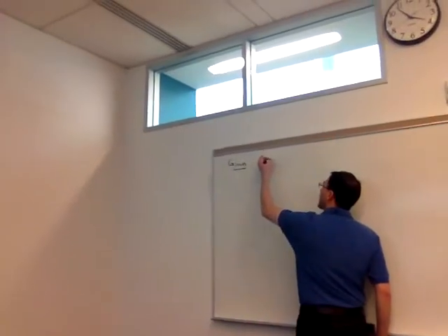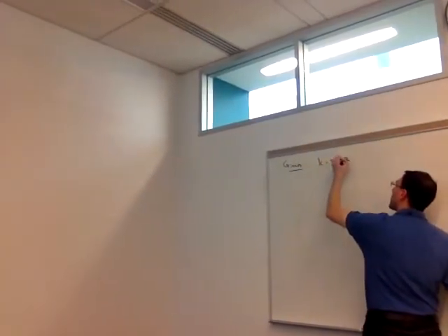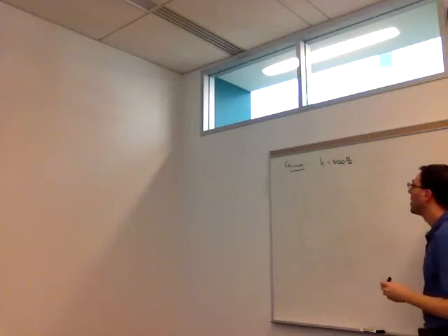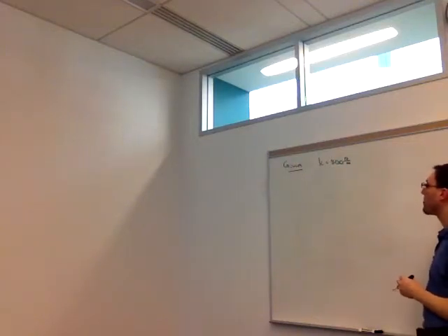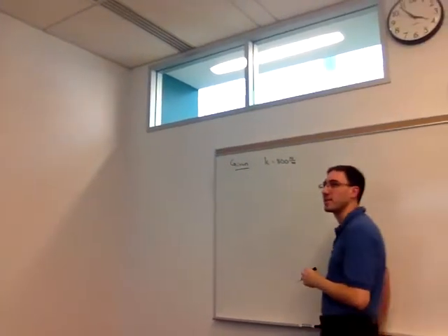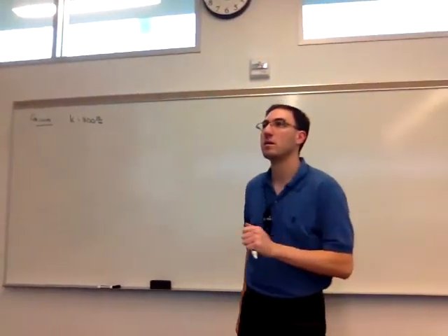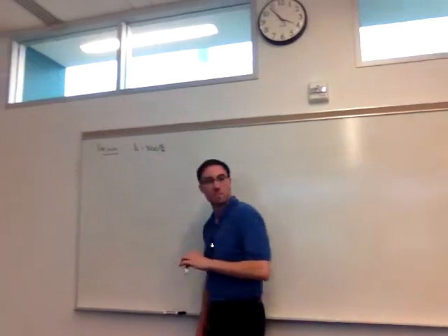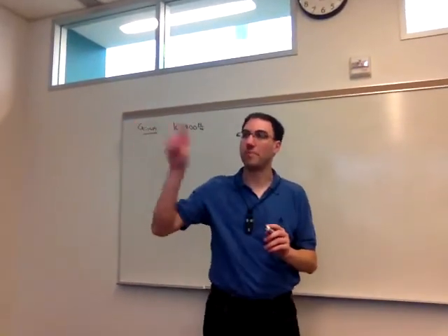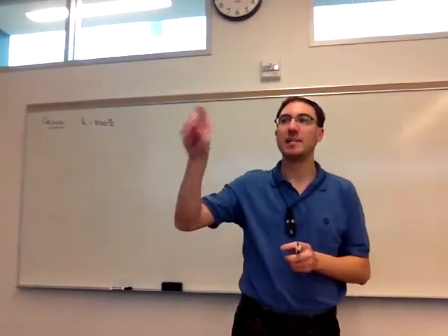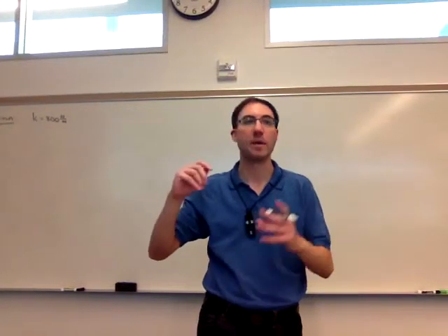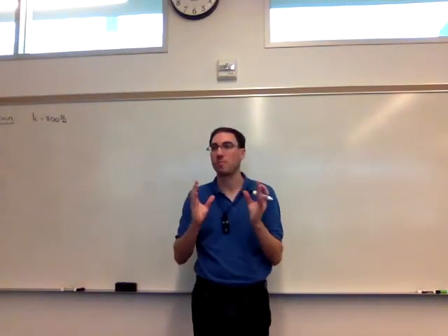Right, so that stiffness of the spring, 800 newtons per meter. And what else is probably going to be relevant that's given to us in the text or elsewhere? Yeah. The 200 millimeters unstretched length and 500 millimeters stretch. Right, so good. You picked up on both of those pieces. The diagram tells us that distance between A and B, the equilibrium length of that spring.